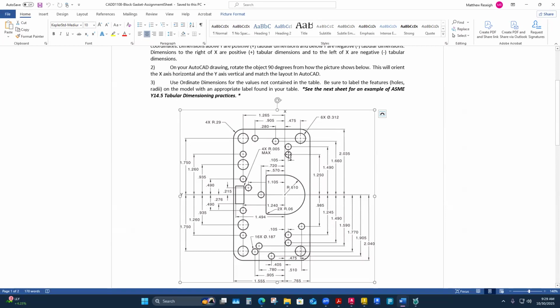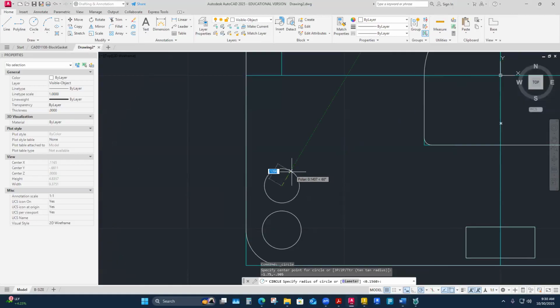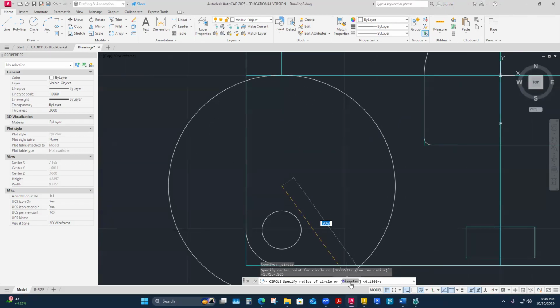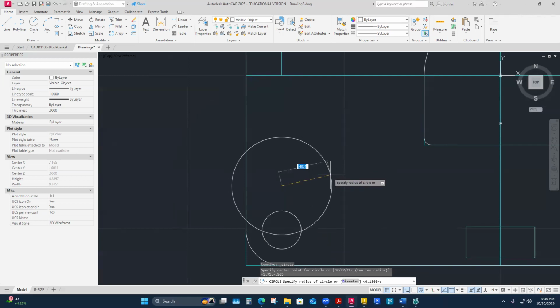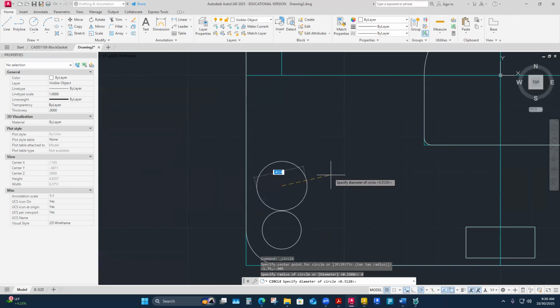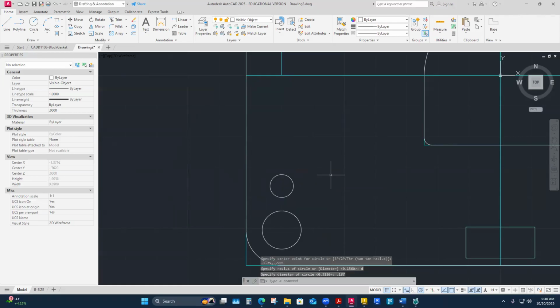So there's really only two diameters of holes in here. 16 small holes, six larger holes, plus the other two: the rectangular feature of size and this other weird one. So I just need to know that diameter. What is it? Oh, yeah, it's 0.187. So I'm back to here. This is by radius. Anytime you're in a radius type circle on the command line, you've got diameter as an option. If you hit D, you can always switch this to a diameter driven dimension. D, enter, or select it on that command line, right? And these are 0.187. Bam.